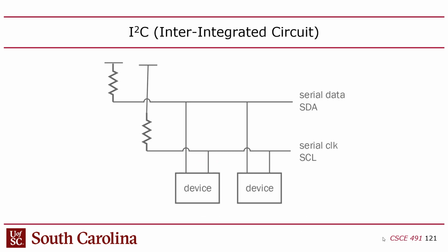Okay, all right, so I2C is a protocol that has 2 wires that form the shared bus, essentially. They're called SDA and SCL. So what does that mean? S stands for serial, DA, I believe, stands for data, and CL is clock, right? So you have a clock and you've got data. And both of these are using the open drain style, right?